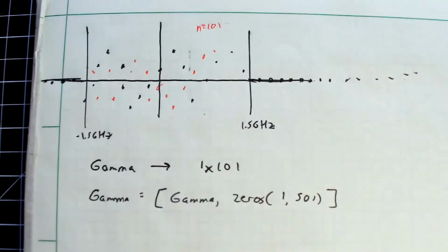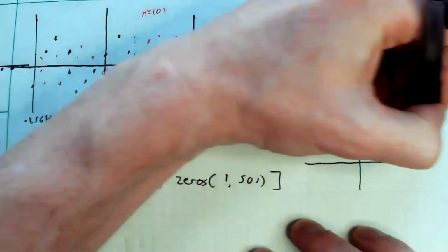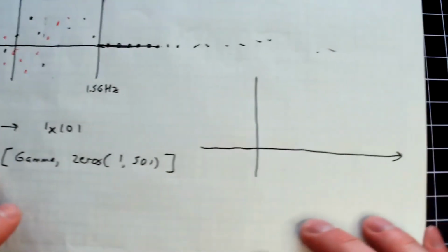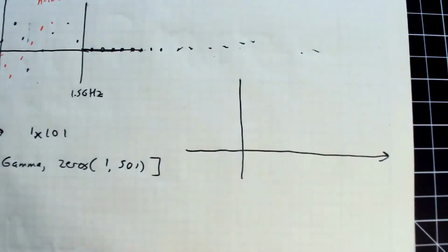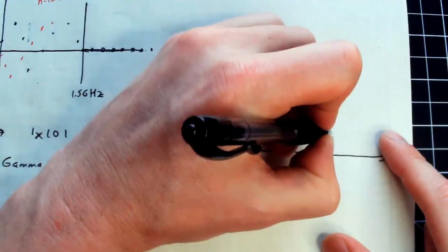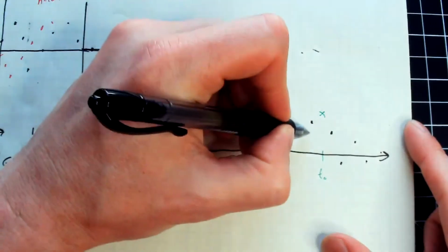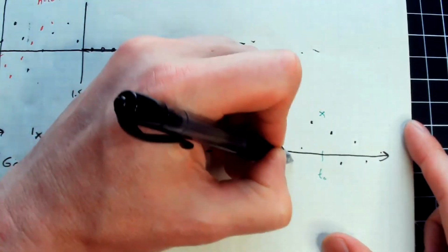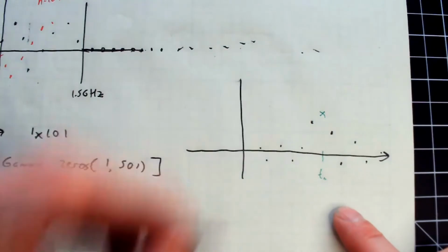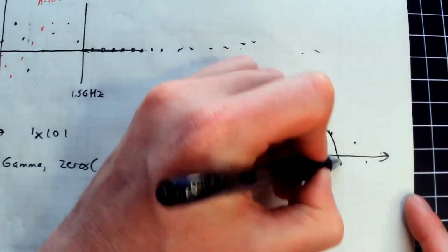So when you take the inverse Fourier transform, you get a neat little effect. I'm going to draw this out here. Originally, you would have a true peak that was maybe right here, corresponding to this time offset. But when you looked at your samples, you tended to see something that looked like this. So when you play connect the dots with MATLAB, you see this peak getting sliced off the top.